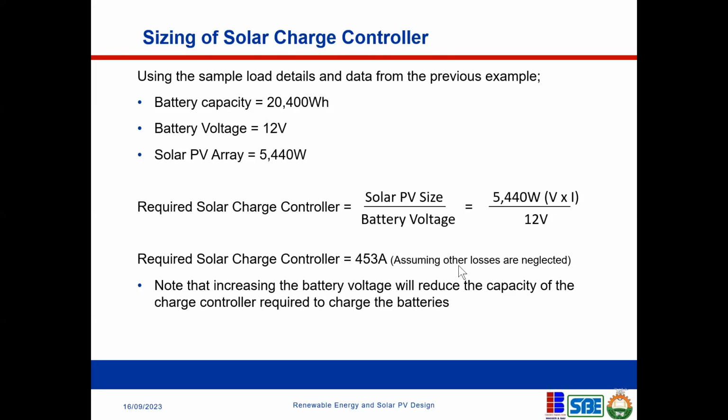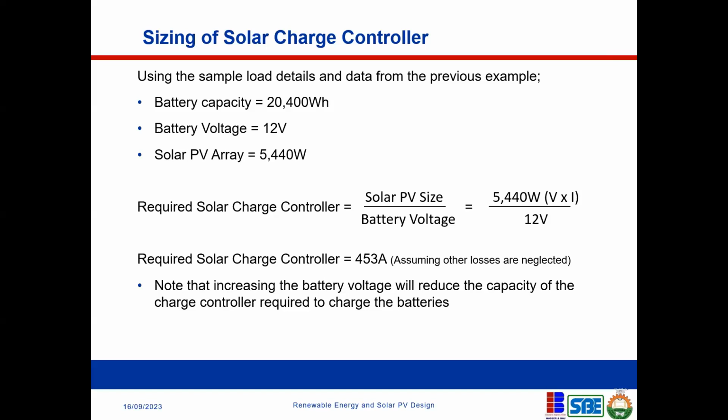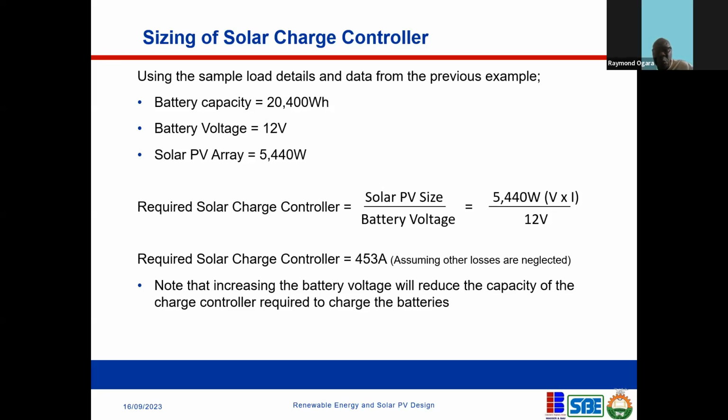As a designer, you need to be cognizant of the cable sizing. You cannot have a higher current and use a smaller cable. You're creating danger, right? So all of this has to come into the balance.